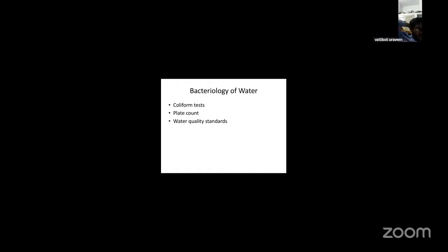What is the membrane filtration test? The water is filtered, and the bacteria are retained and counted with culture media. What is the plate count? Plate count is also called the standard plate count (SPC). It measures the total number of viable bacteria in water.